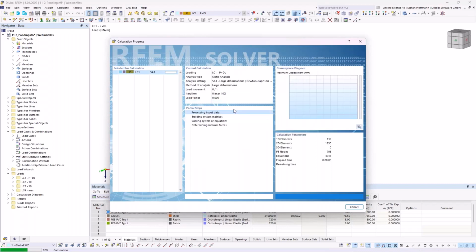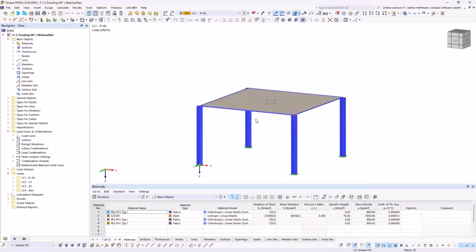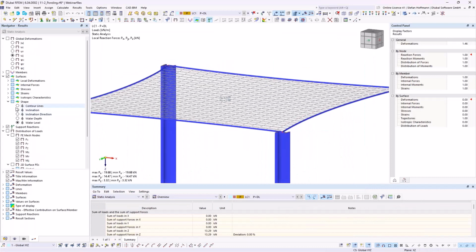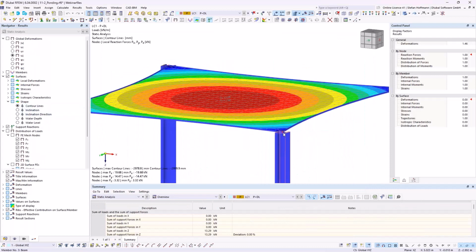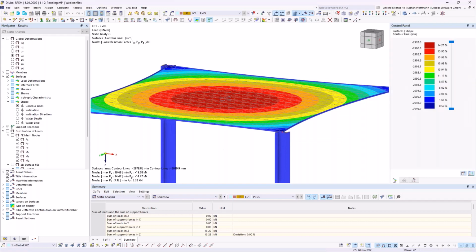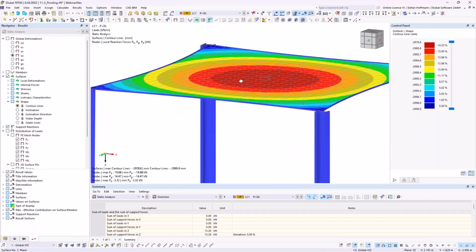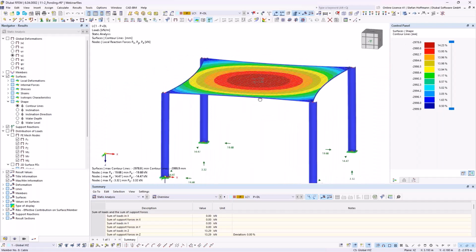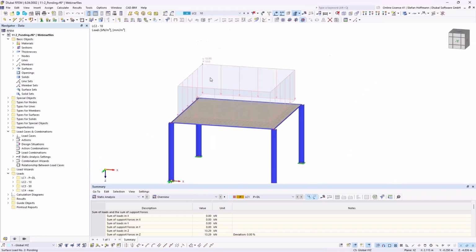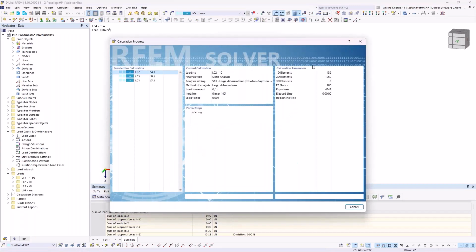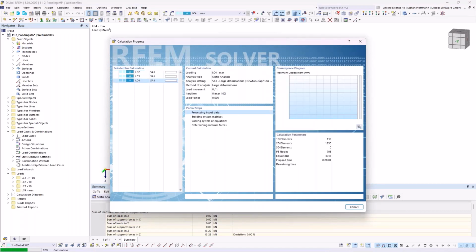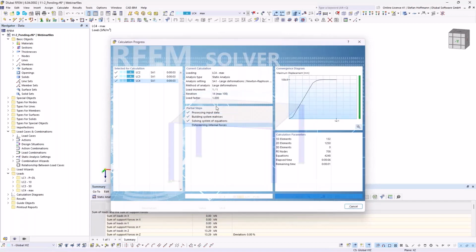So due to the minimum dead load, there will be some starting shape, which you can check with the contour lines. So this is a 3-meter member height, and we have like 2 centimeters of deflection already in the Z direction. So if it now rains, I've chosen 1 times 10 millimeters, 50 and a bit more, so the full way. You can now see it a bit better because it's a quite easy structure to observe how the rain will then fill your construction.